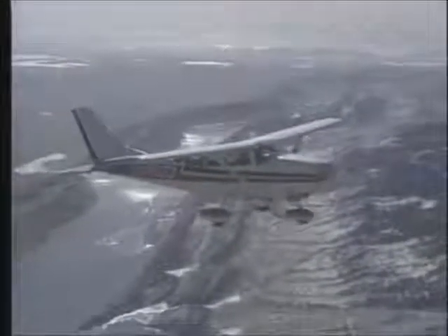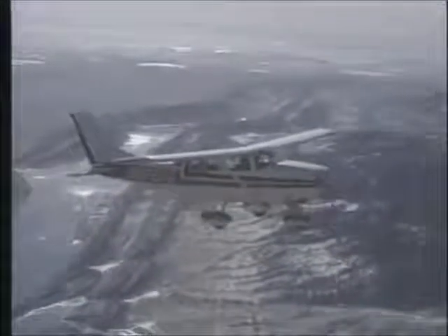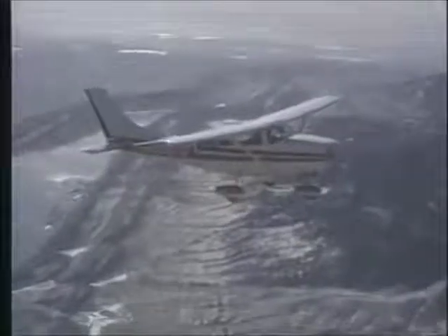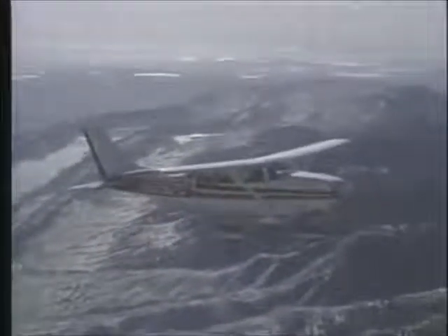Whether you fly airplanes with a carburetor or fuel injection, engine efficiency decreases as you gain altitude, and thus the density of the air entering the engine is reduced. To overcome this drawback, some engines incorporate a turbocharger that compresses the air that enters the combustion chamber. This increases the density of the air. Ultimately, the airplane is capable of operating at higher altitudes since the engine can continue producing sea-level power as you climb.